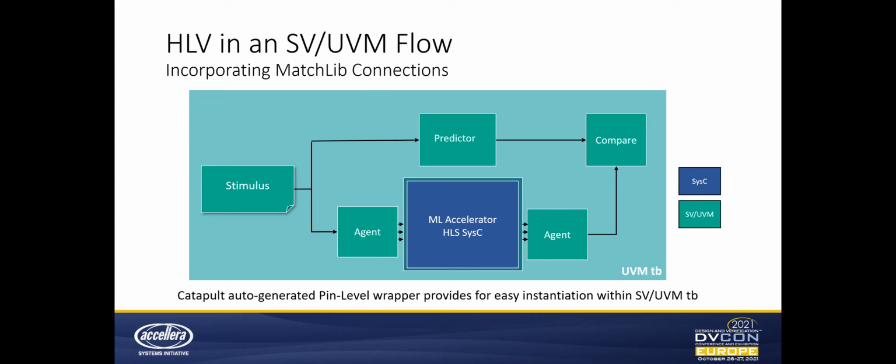Once you get to this point, you have the ability to carry out a majority of your verification against the pre-HLS design, which again is available much earlier in the process and will result in simulations that typically finish a good deal faster than an equivalent RTL simulation. Once you're ready to switch gears to target the RTL instead of the pre-HLS source, doing so is as simple as compiling the RTL instead of the SystemC and its wrapper, similar to how you might swap your RTL out for a gate level equivalent.